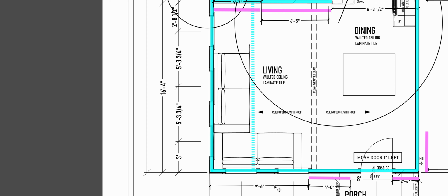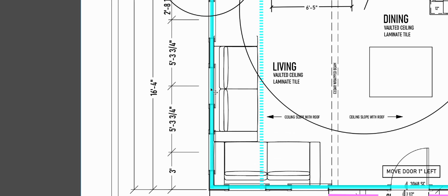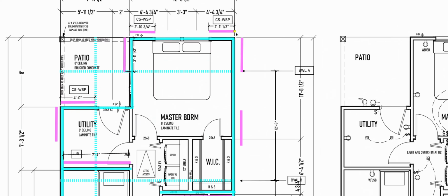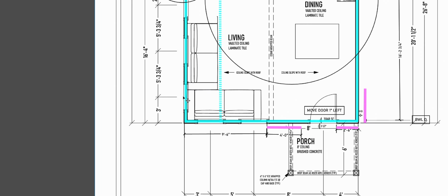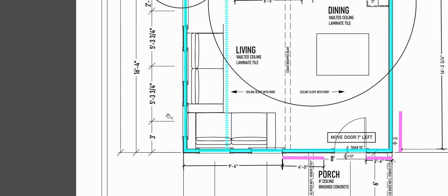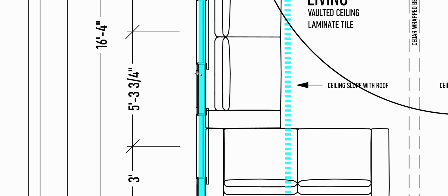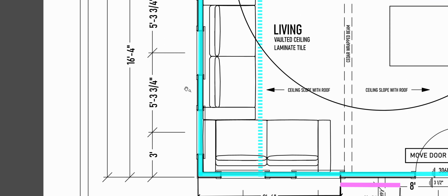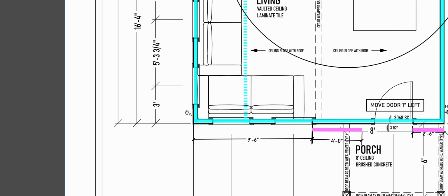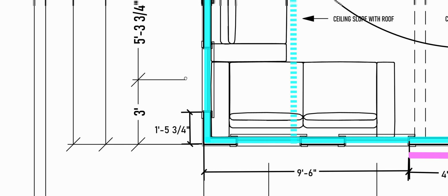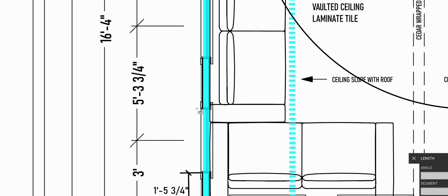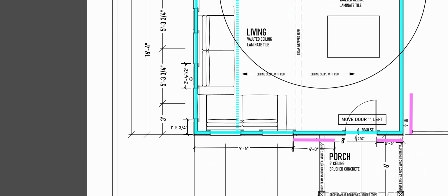All right. So these are some skinny walls. I can tell you right now, these are probably not going to work. Now, all the windows are the same. They're all the 3050 windows. And back here, I knew that a 24-inch was my minimum for the panel. I've got the same thing going on because I have an 8-foot wall right here. So if I'm lucky and I have 24-inch spacing between these windows, then I can do this. Because I can't fit it there. That's just not 24 inches. Nope. Maybe this is 24 inches, 2 feet. Do I have 2 feet? 2'4". Cool. Well, I got lucky.